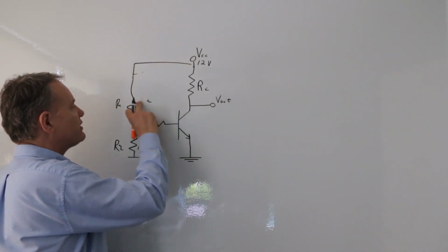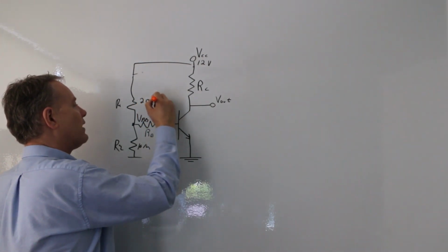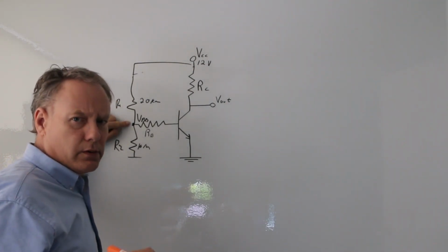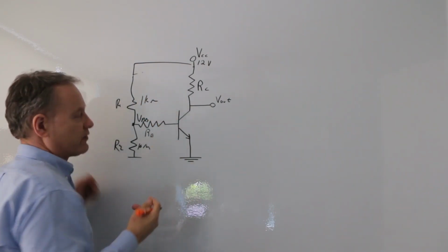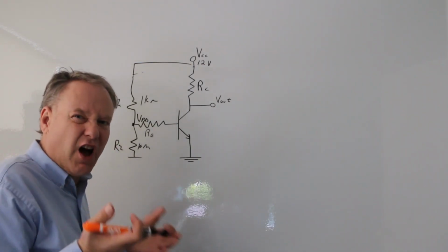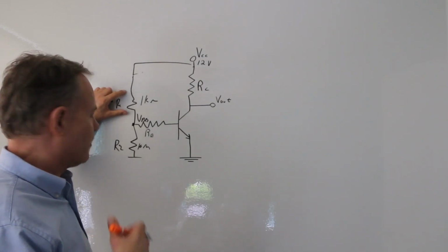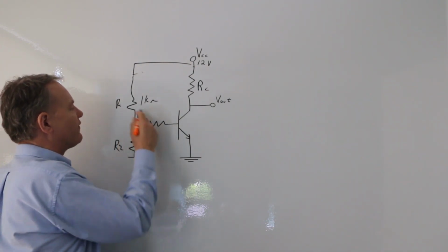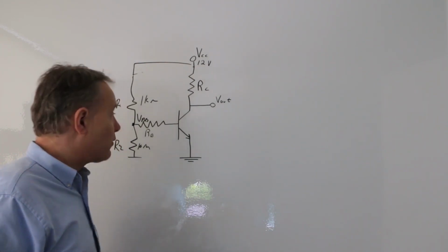Now, if for some reason this resistor was changing its value and it went up to 20 kilo ohms or higher, obviously my VBB would go down. The other thing is, if I were to change this to a 1K ohm, because the nature of a thermistor does that, and other things as well, force transducers and things. Stuff changes resistance depending on what it's designed to change resistance on. And now we're seeing a varying voltage at VBB. So that's actually how we're going to design this.